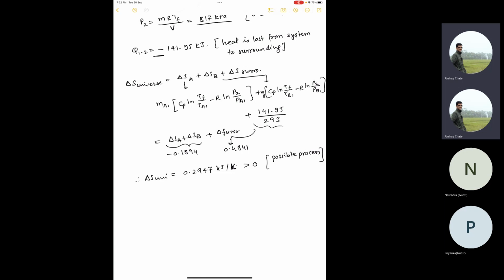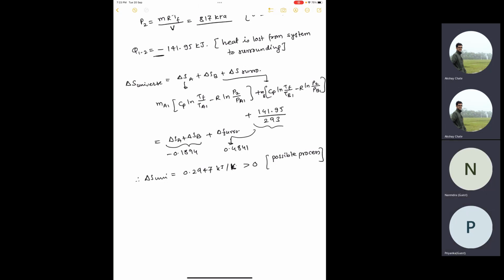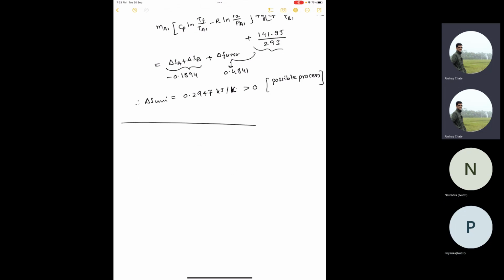Essentially, they are doing the same thing, but this is a confusing way of writing. And they have not mentioned that they are neglecting that m Cp delta T. It will be a very low value. We can solve this here itself. Do you have a steam table with you, Priyanka? Steam table, yes, sir. So I just need the hfg value from you. If you can see my screen, I will write it as m Cp delta T plus m hfg at 0 degrees Celsius.